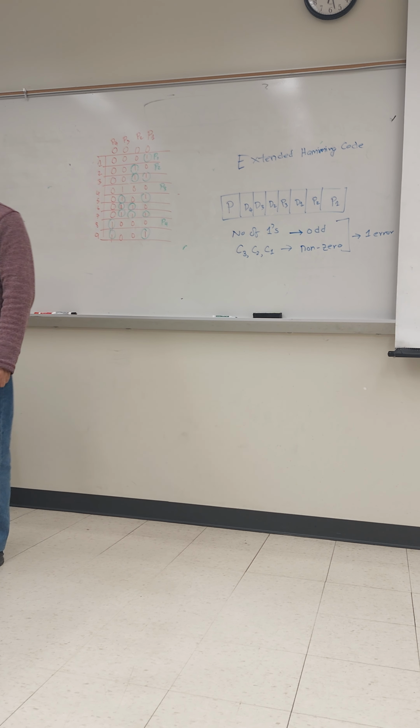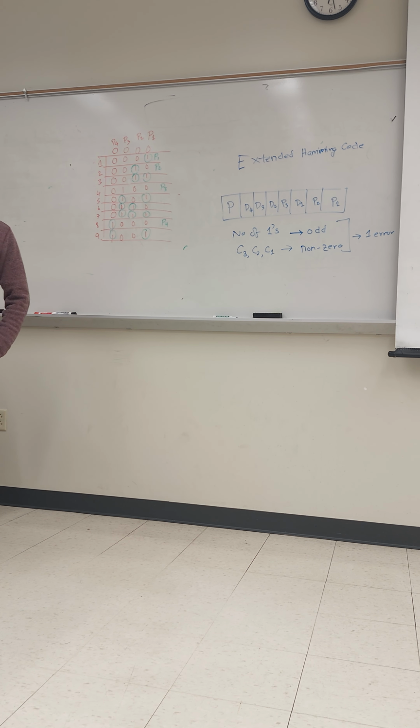If you go to the second case, I mentioned that whatever we transmit, we receive the same signal. That means no error. If there is no error, what will happen? The total parity bit will be even, and C1, C2, C3 will generate 0. That means there is no error. It's very simple.